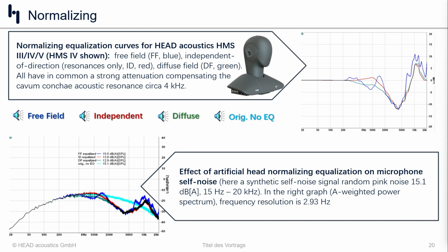This is why the low noise head was created essentially for the IT industry. But right now the issue is coming up, and I'm recommending to some people working with quiet EVs and tonalities that they consider the low noise head. Because, and I'm going to demonstrate from actual recordings in the same chamber at the Aachen University with the same test object, where the two heads were on opposite sides of it in the same chamber, the improvement in the noise behavior. And unfortunately, there's low frequency rumble in this chamber, which is kind of dominating, but you can still hear the difference. So the LN would be their standard.